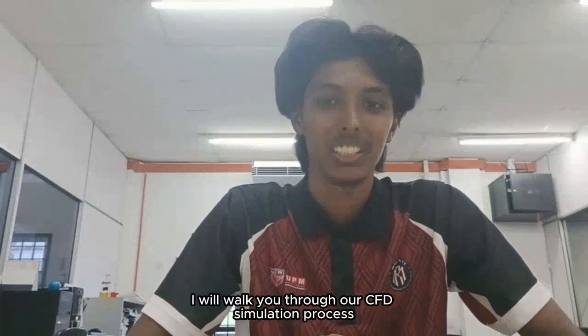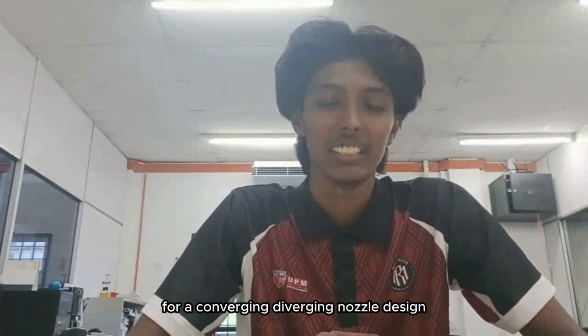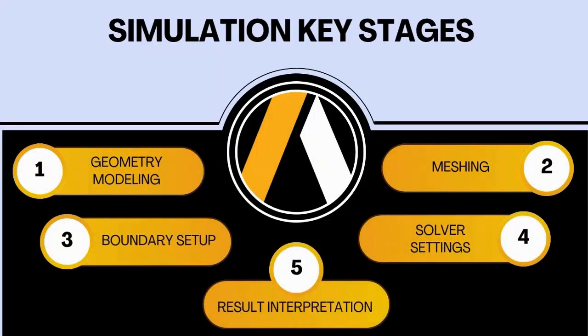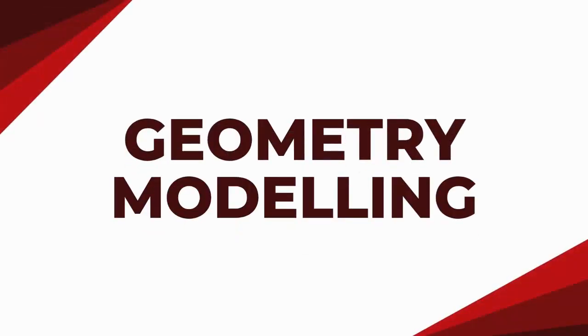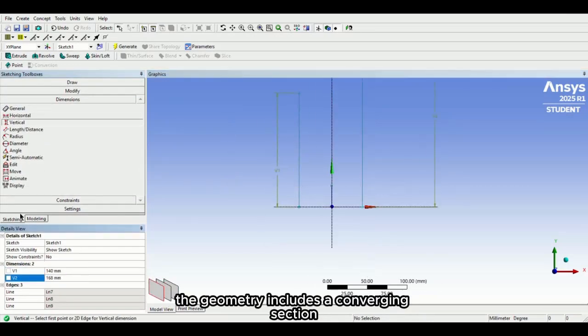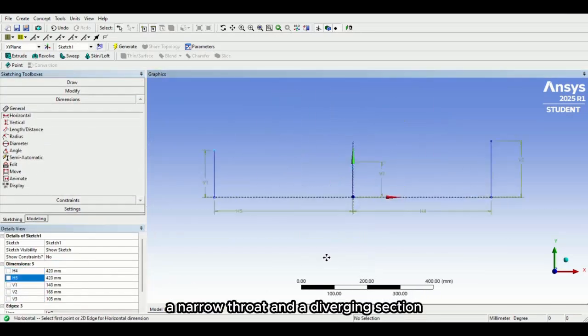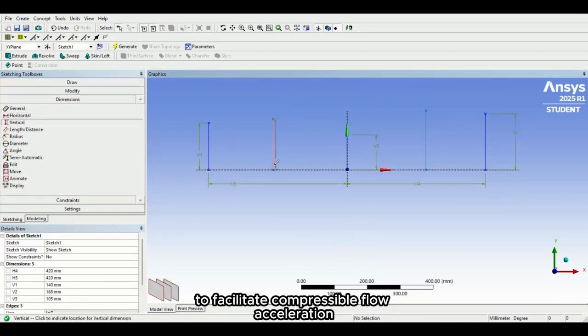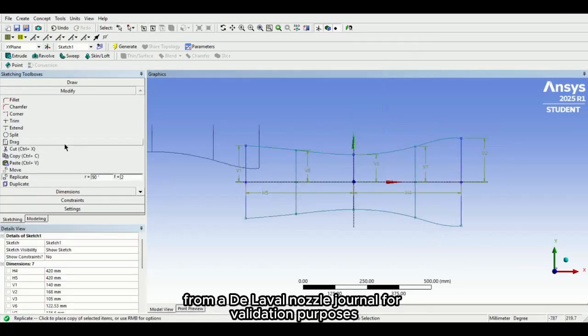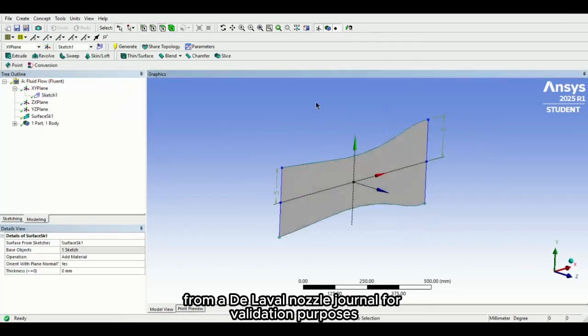In this video, I will walk you through our CFD simulation process for a converging-diverging nozzle design. This involves key stages which are geometry modeling, meshing, boundary setup, solver settings and result interpretation using ANSYS Fluent. First, we design the nozzle using Design Modeler. The geometry includes a converging section, a narrow throat and a diverging section to facilitate compressible flow acceleration. The design follows reference dimensions from a de Laval nozzle journal for validation purposes.